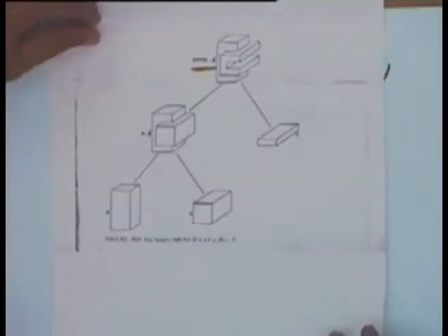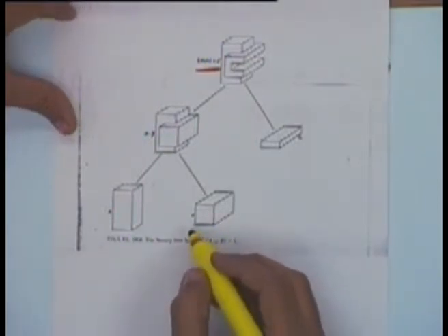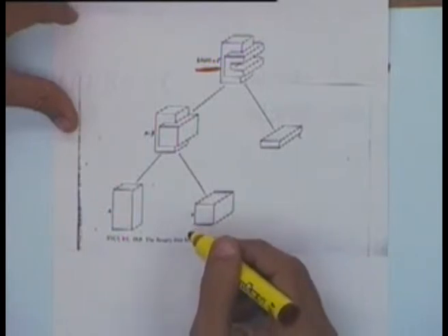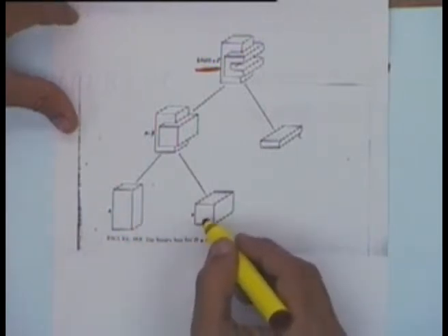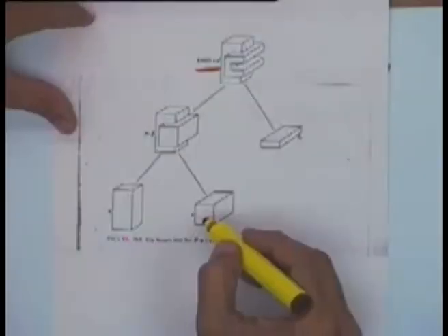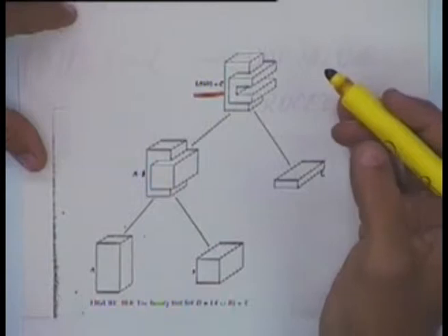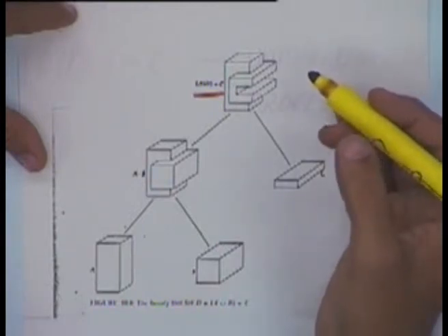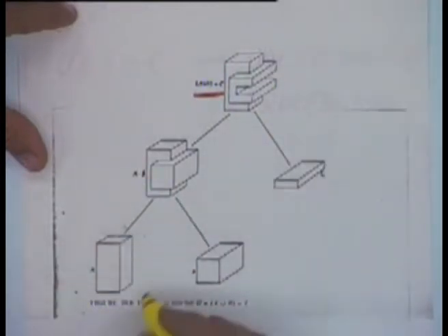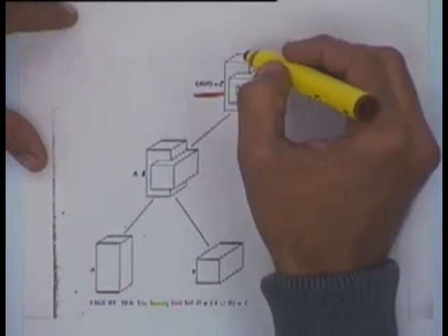Okay, the primitives, like in this case, will be represented using some other modeling technique, let us say BREP. There can be other modeling techniques that we use for that. Right now we will talk of only the BREP. If you are using some other technique here, when we evaluate this model, this solid will also be represented in that technique, not as a BREP normally. So whatever method we are using for representing these primitives, after evaluation we will try to get this model also in the same representation.